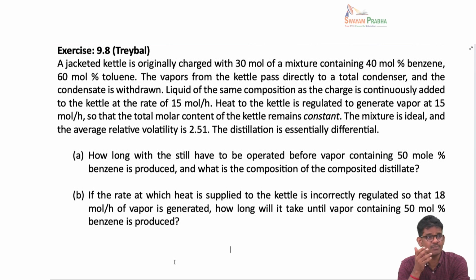And there are many modifications to this differential distillation. This is one of the operations where you try to maintain the liquid in the still constant by charging a fresh feed continuously. As much as you take the vapor out, an equal amount of liquid you put in, so that you operate under a steady state condition.